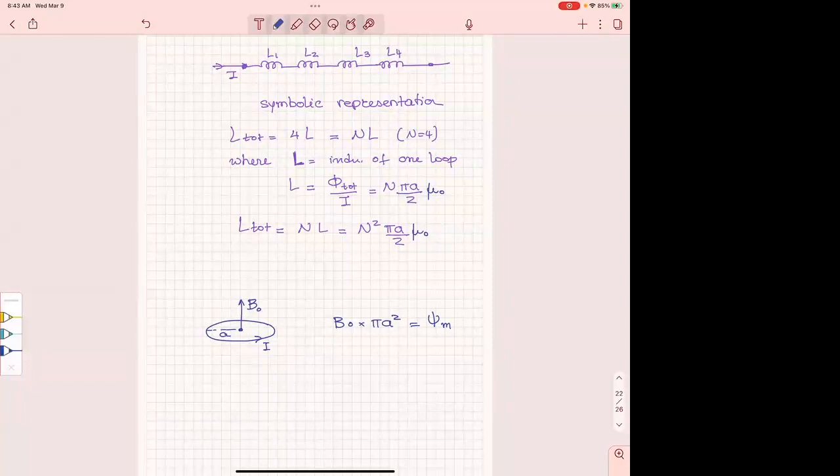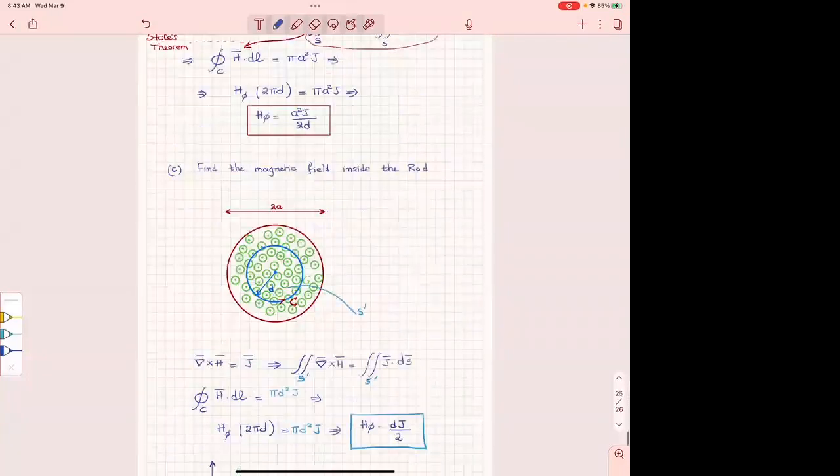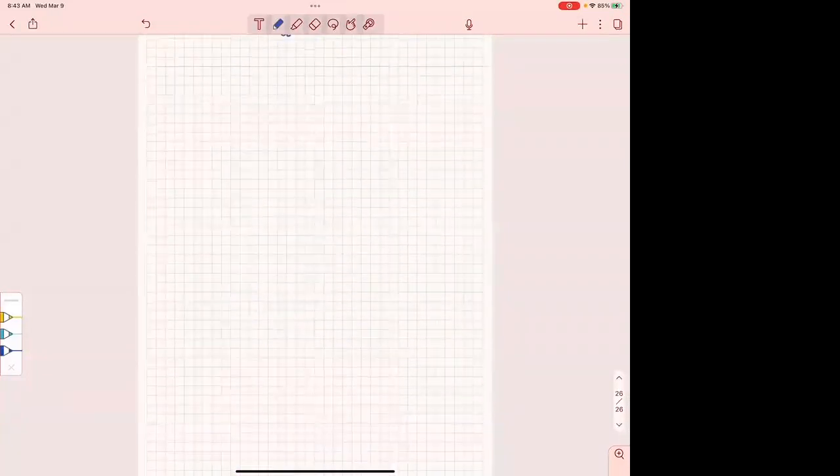All right, and then for this particular case, if you multiply the total magnetic flux for the individual loop by n squared, where n is the number of loops you have, and divide by the current, then you get the total inductance. Now, what we want to do next is the following. Let's assume that we have loops, but they are in a solenoid.